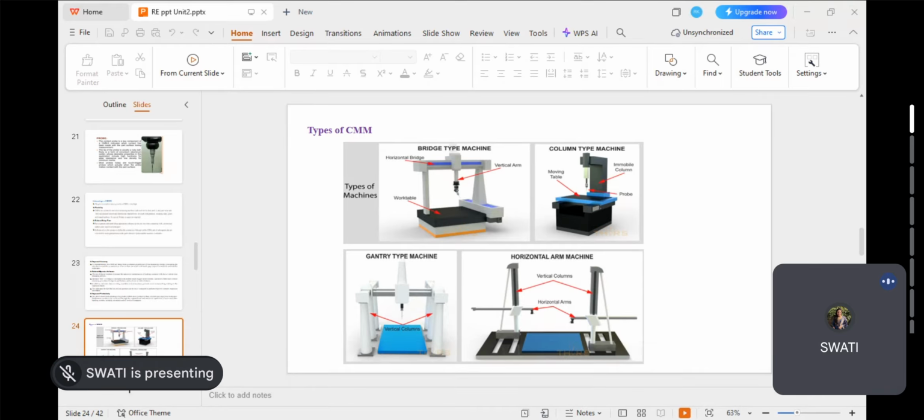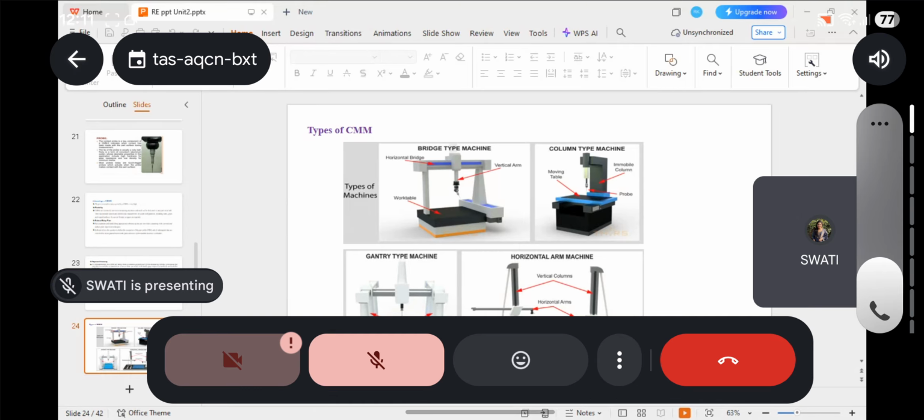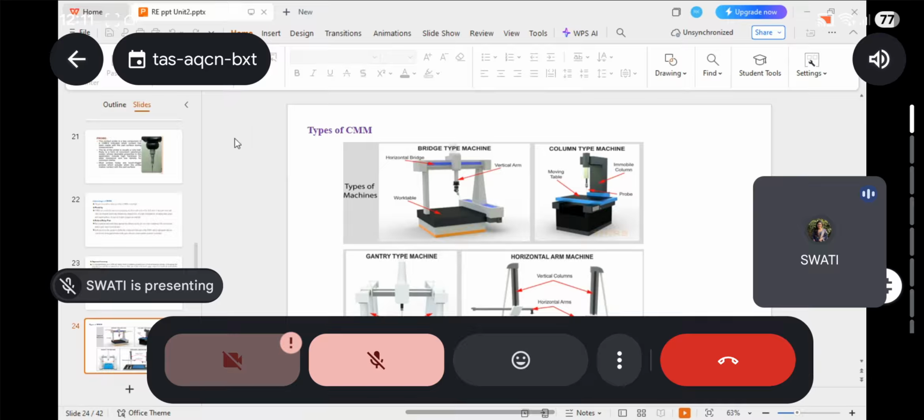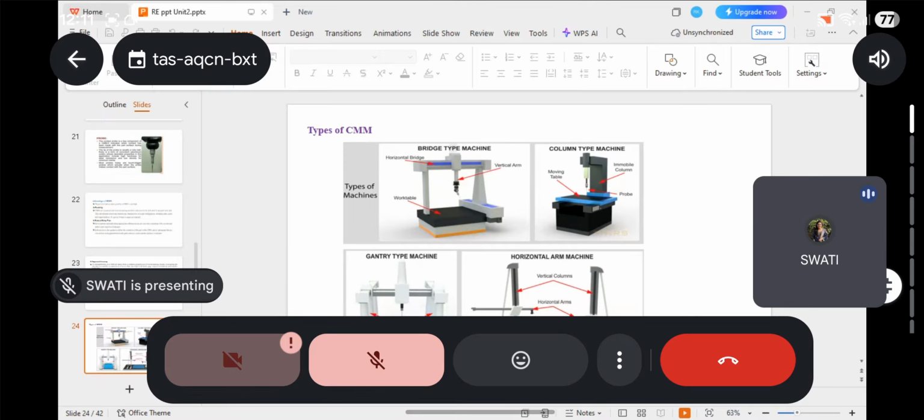So you can use some kind of excess material if you have, but you have to be very careful that the sides of the machines should have a certain kind of space, so that the particular part can be manageable in that particular domain. Okay, so this is about the cantilever type of coordinate measuring machine. If you compare cantilever with the bridge, the bridge can occupy a larger size of component, and cantilever is specifically for small and medium sized machines.